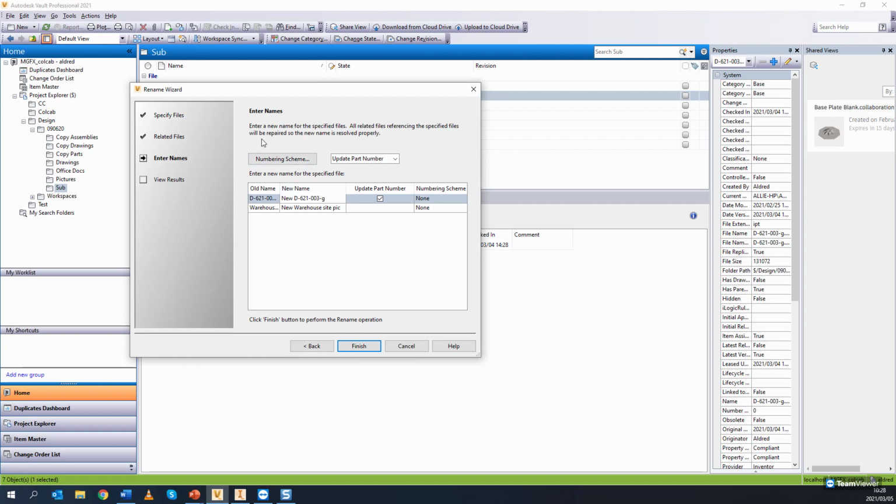So you'll see a numbering scheme. What you can do in Vault is put an automatic numbering scheme into Vault, so that whenever you create a new part or a new assembly or subassembly, you can automate the numbering. I know a lot of companies use an Excel spreadsheet, and whenever you create a new part, you need to go to the spreadsheet and tick off the next number on the list. It has to be shared between a whole lot of people, and you need to make sure you cross off what you use. Otherwise, you start duplicating part numbers and file names of certain parts.